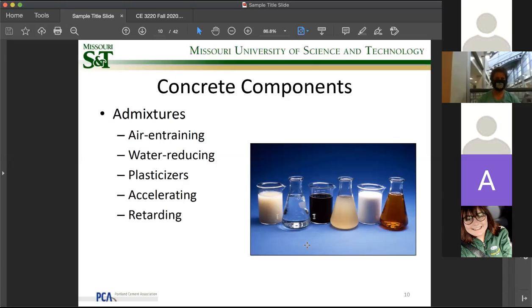But the problem with that is, with long time exposure of polymer to water, the workability dies out pretty fast. So plasticizer is more like a dynamite, right? You throw it in, it works like a charm. It gives you an hour or 2 hours of working time, but after that, the concrete starts to set, flash setting immediately, okay? So that's the function of plasticizer.